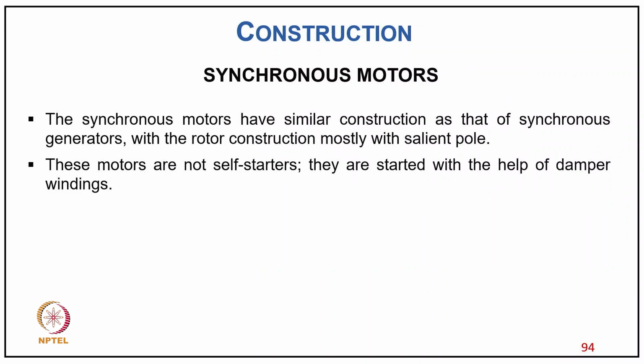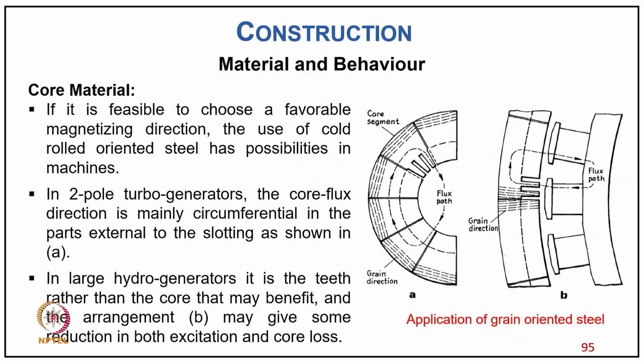Now coming to the synchronous motor. The synchronous motor has a similar construction to that of the synchronous generator, with rotor construction mostly with salient pole. And these motors are not self-starting, so they are started with the help of damper winding. Now coming to material and behavior.